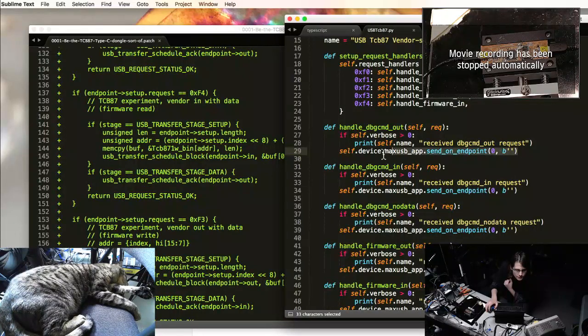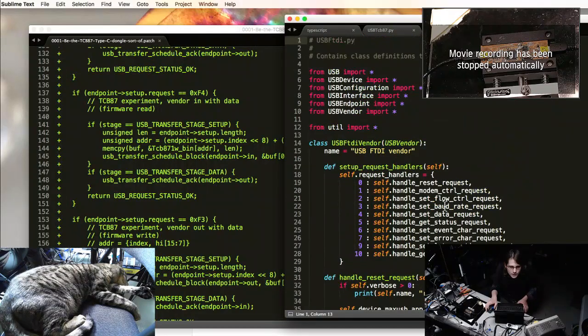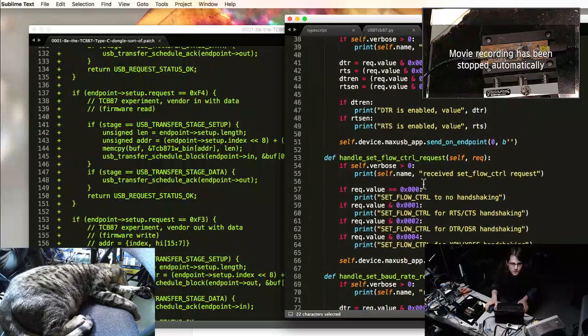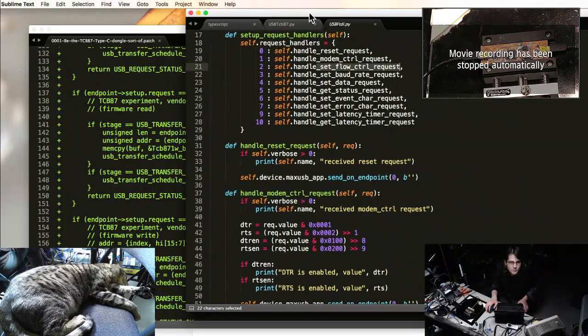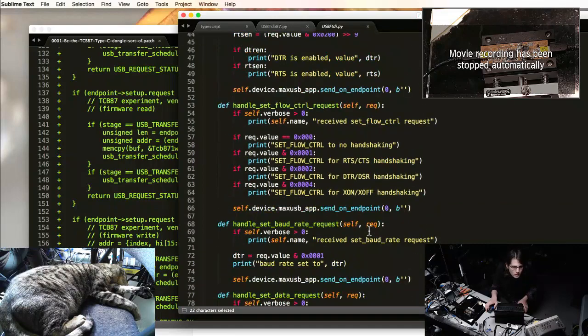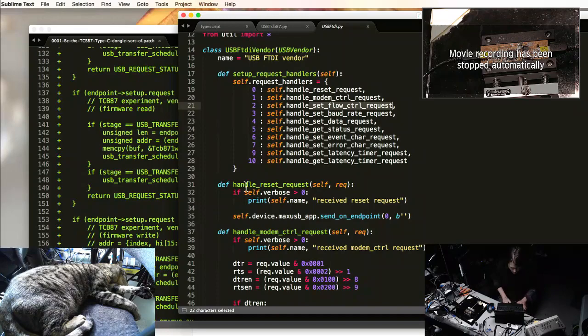This is fine for an acknowledgement, but to get the actual data, I also need to figure out how to read that buffer. I don't think the FTDI had any commands like that, because stuff like these setters just use the parameters baked into the 8-byte setup packets. So let's see what else we might be able to do.